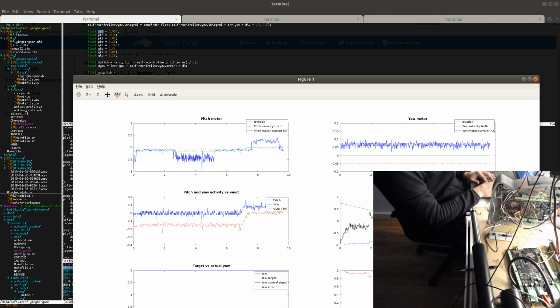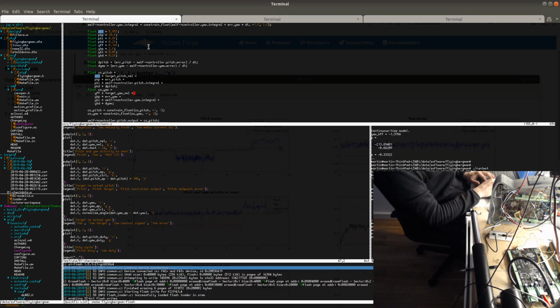And in this particular case, I don't like to use the integral, because the integral would give me an overshoot. So I set the integral to 0, and I instead use a higher Kp value to get better response to any errors. And I also use the feed-forward value to get instant response from the controlled system.